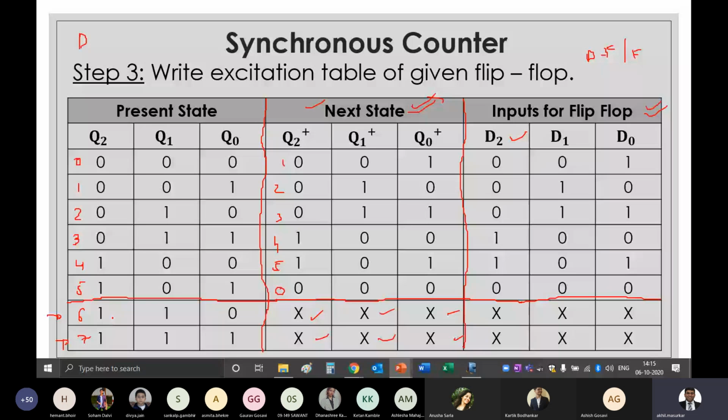You can observe these conditions many times at the station. I have observed that many times the station indicators show some value like FF, E, CD, something like that. What has happened is that the display has gone into lockout, and the only way to bring it back is reset. So the design has to be such that the counter never locks out. That is the reason why, instead of defining these last two don't care conditions, we can define them as 0, 0, 0. That is quite possible.